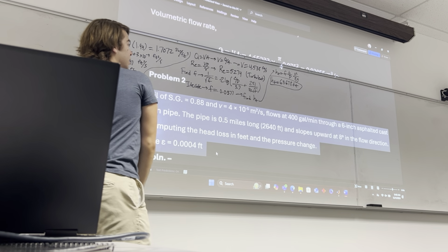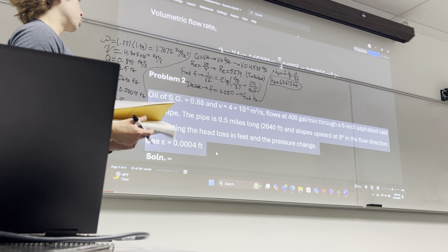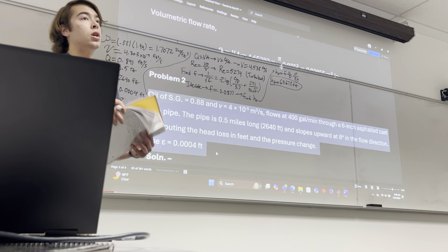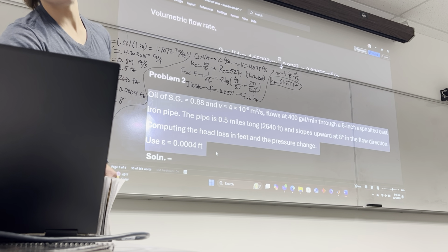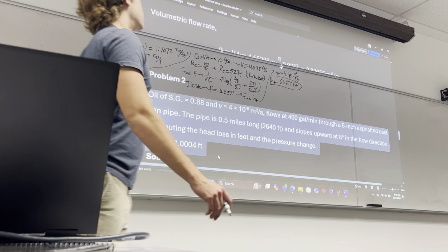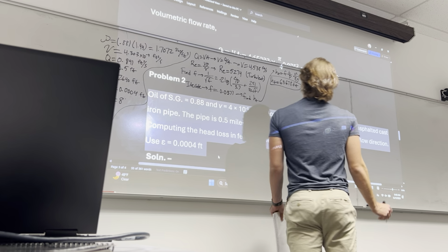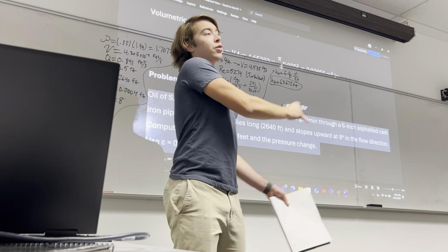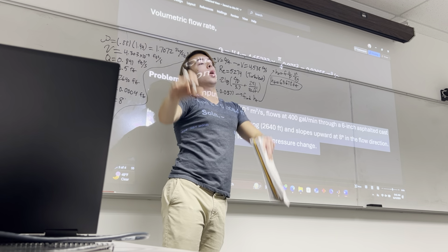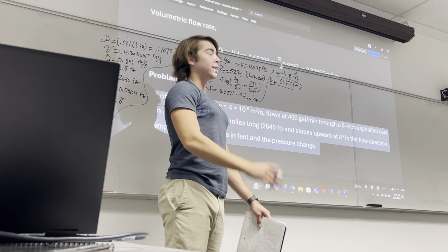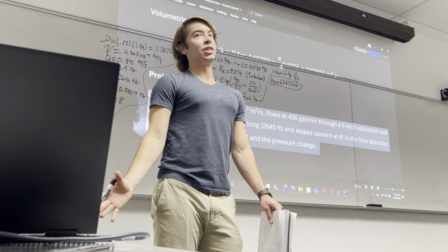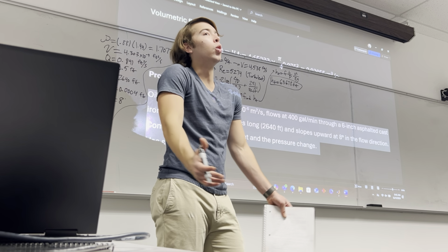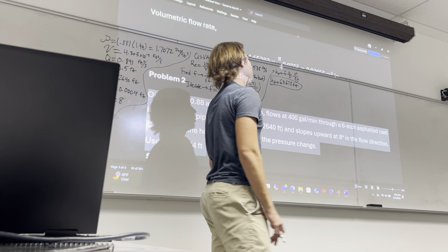Cool. So now we want to find the pressure change, right? For the pressure change, you use that Bernoulli's-ish kind of equation where you have all sorts of pressure terms. We're going to assume this is coming from a big reservoir and going into a big reservoir. It doesn't explicitly state it, but like 90% of things in this class, you just have to assume stuff. Write down what you assume, it'll be fine.